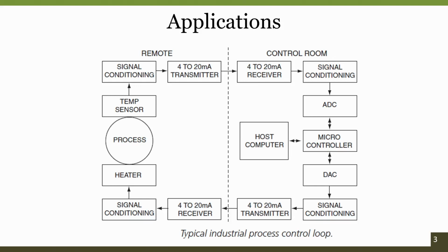And in case you have an application where, based upon the input that you have analyzed, you have to actuate something, then as the microcontroller deals only with digital signals, and your real world signals are analog, you have to convert the digital to analog using digital to analog converters. Moreover, these converters cannot provide the power required for your actual actuators. As a result, again they use signal conditioning circuits to match the input power with the output power, and transmit as usual,